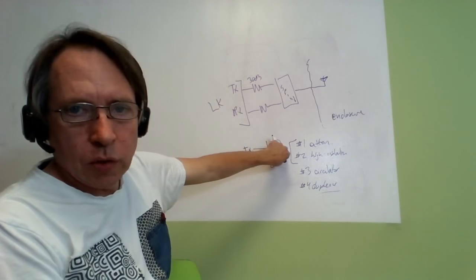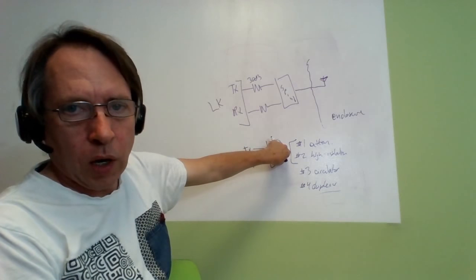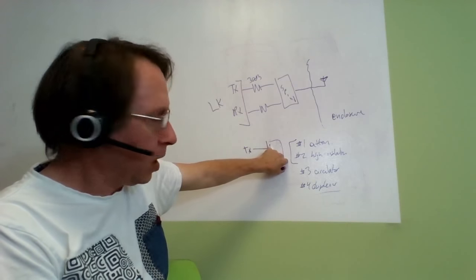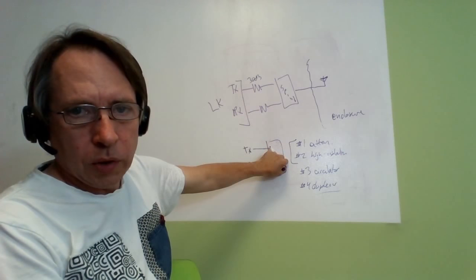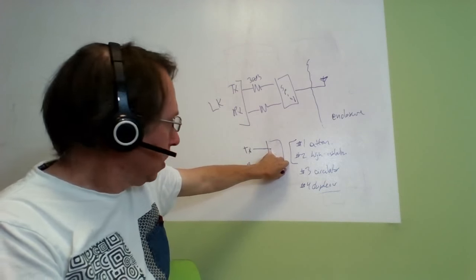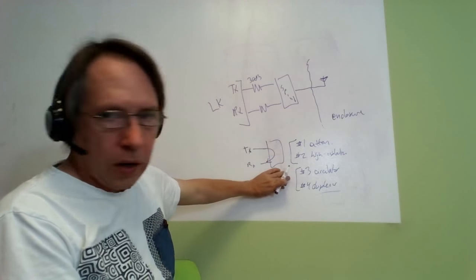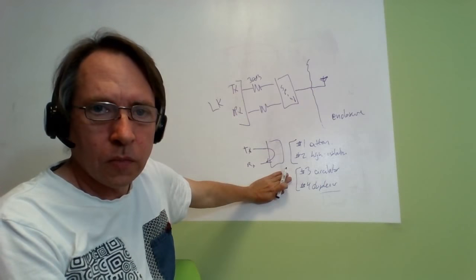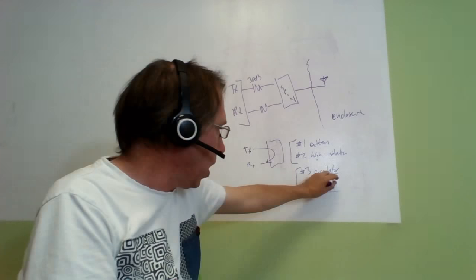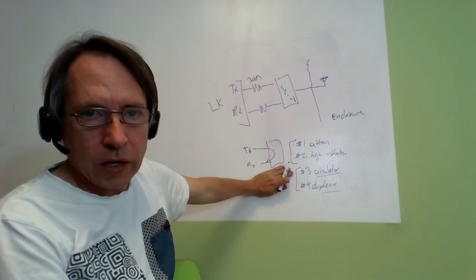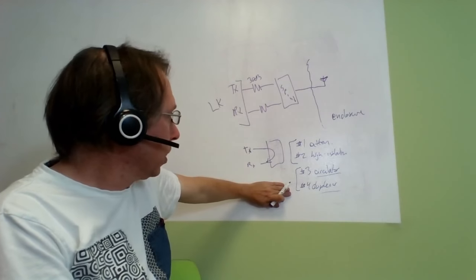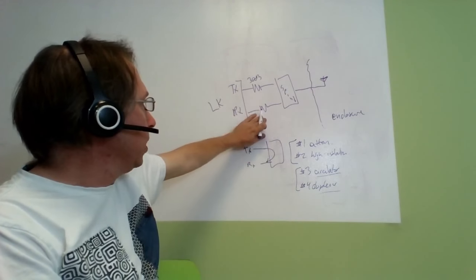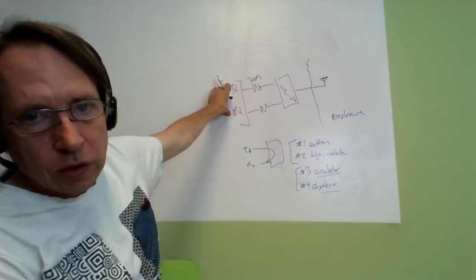These two solutions are very wideband solutions with attenuators or high isolation splitters. You can build a test fixture that'll work for just about any LTE band. These solutions are not so flexible. They're all wideband circulators that might work for a wide range of bands, but not for all of them. And duplexers are most definitely band specific. So when you're working, especially in FDD bands, this question of self-interference and self-jamming is important.